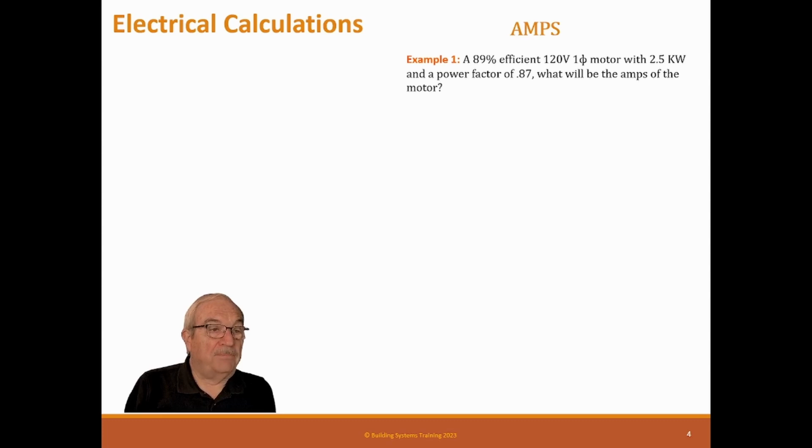So that now people are paying for power, not getting the benefit of it. So it's really important. And they use capacitors to bring the power factor back into line. Electronics actually also does it. So a VFD can actually be used to increase the power factor because it's adjustable. So anyway, you can do this.